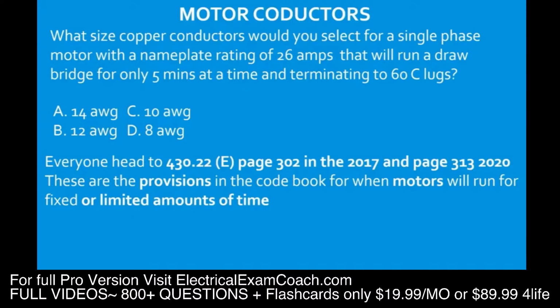Starting on the left-hand side is going to be our classification of service. On the left-hand side, we're going to pick whatever scenario our question lists. If you look down through there, somewhere you're going to find something about a drawbridge, or whatever your question states. Then going across the top in the black bold headings, you're going to see 5-minute, 15-minute, 30 to 60-minute, or continuous duty rated.